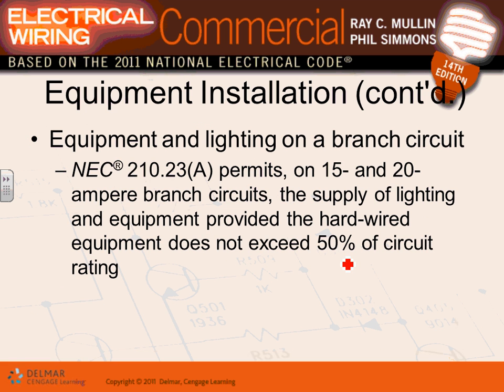The NEC code book applies to all of them. A couple of things, guys, about sharing. Adam, the rule when it comes to equipment, guys, is individual dedicated circuit. If you have an appliance or a machine in a commercial industrial building, you give it a dedicated circuit. Now, can you share circuits with lights and receptacles? Yes. Is it a good idea? Absolutely not in a commercial industrial project.